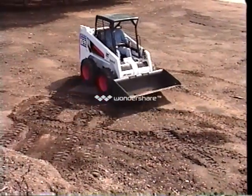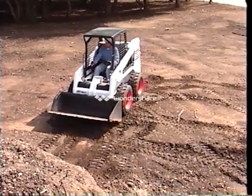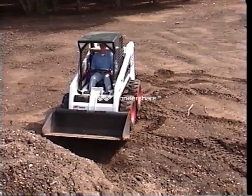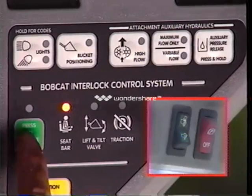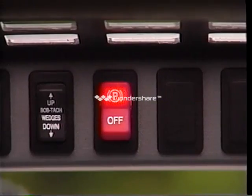Now we will learn how to select the ACS mode and operate the loader's lift and tilt functions using the Advanced Control System. First, stop the loader. Then select hand controls on the instrument panel ACS selector switch to operate the loader's lift and tilt functions with advanced hand controls. Activate the Press to Operate Loader button on the left instrument panel and release the parking brake before operating the loader.